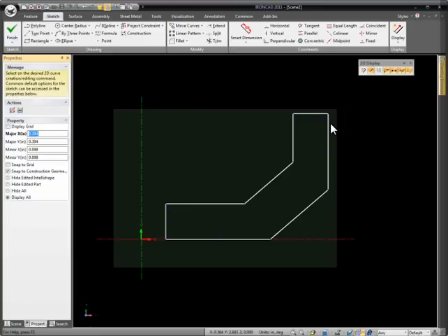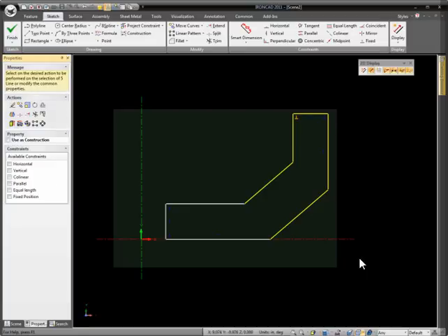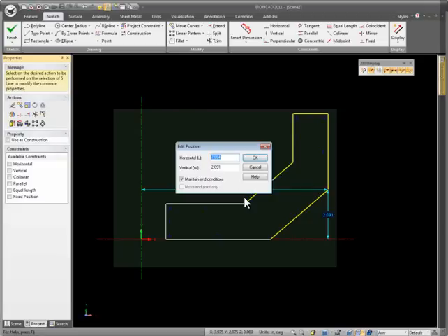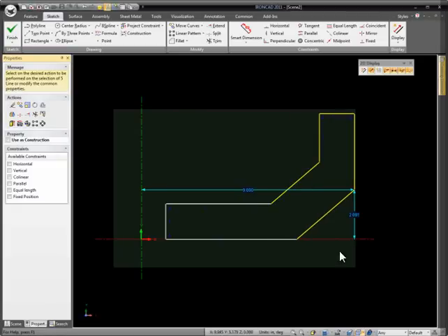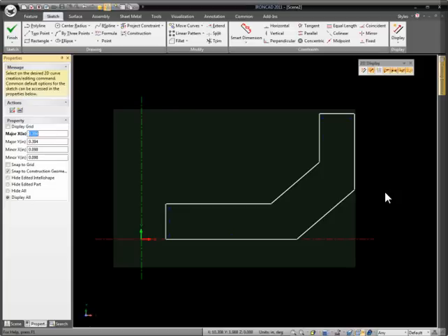The other nice capability with the endpoint dimensions is it can be used on a group of curves. For example, maybe we want to move all these elements that we have selected here. We can box select those, select one of the elements, and we get a display for the position information. We can simply double click that and say maybe we want to set that to 9. We can move all those elements out a certain set distance, which is very handy in positioning your sketch.